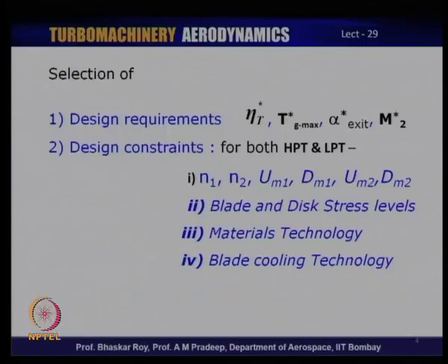You may have a stress limit constraint, the compound stress limit, which puts a limit on the rotating speed, a corresponding limit on the blade speed, and a corresponding limit on the blade size or the diameter of the blade. All of them put together essentially put some kind of constraints on the stresses that come on the turbine, which when compounded with the thermal stresses indeed put a huge stress constraint on the turbine blades.